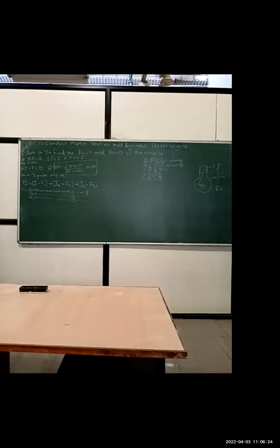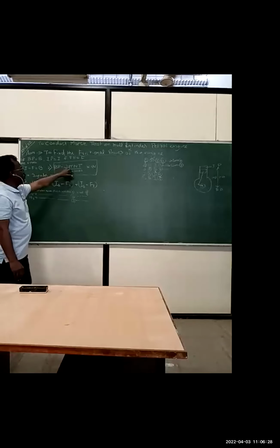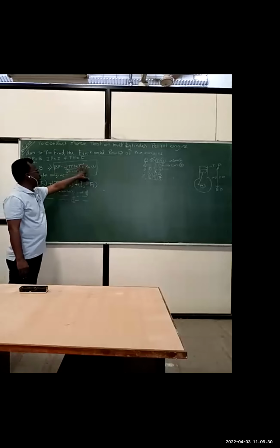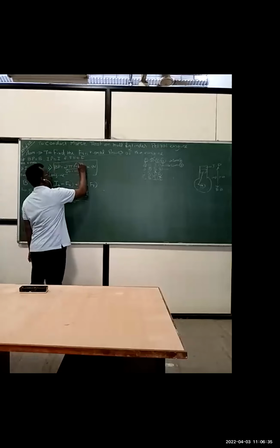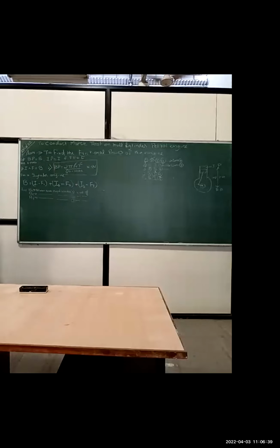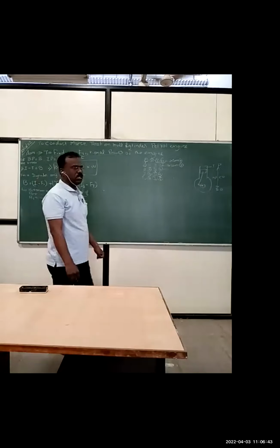Thank you. So, sir, आता आपण इथं काय करणार आहे? So we have BP is equal to 2 pi NT upon 60,000 into kilowatt. This formula everybody knows, where N is the speed of the engine, RPM of the engine, and T is the torque of the engine. Depending on which type of dynamometer you are using, the formula for finding out the T will be different.